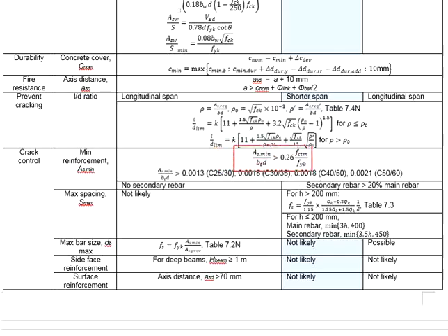You may use this formula for you to calculate the AS-min. This formula can be found in Eurocode. Whatever AS-min that you have calculated here, make sure it is not lesser than the ratio stated here. The ratio varies slightly based on the concrete grade. The higher the concrete grade, the larger the ratio. The equation here, you can get it from the Eurocode. As for the ratio here, I believe it is not found in Eurocode.